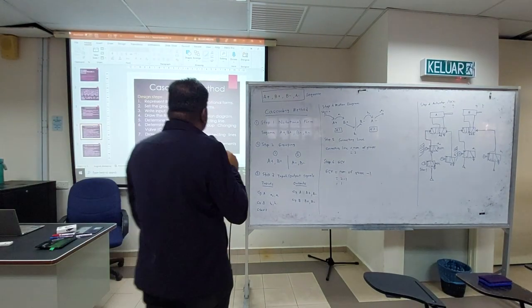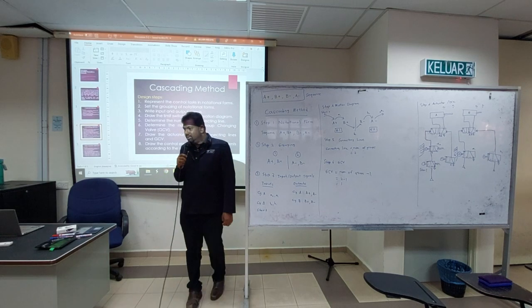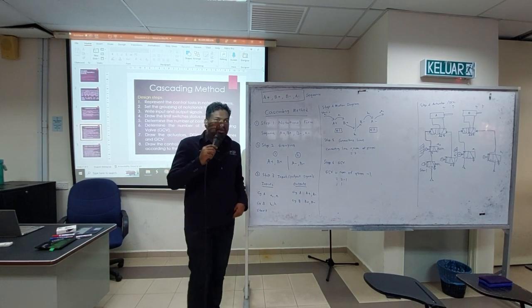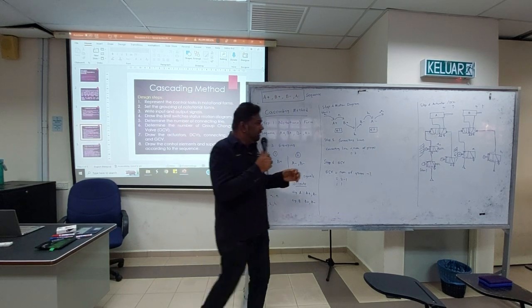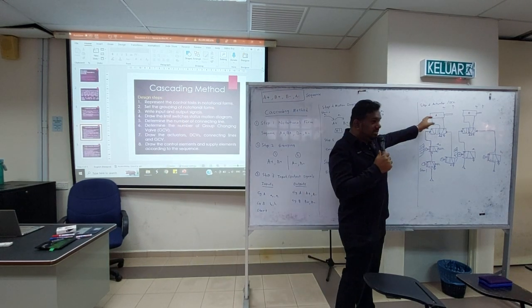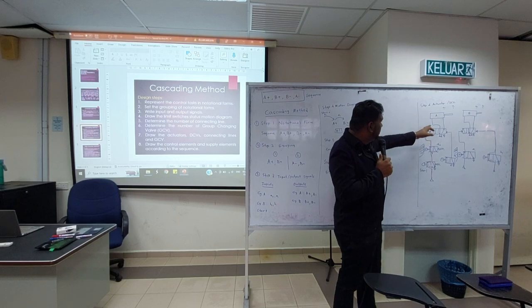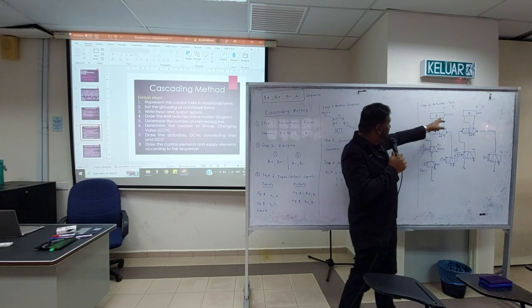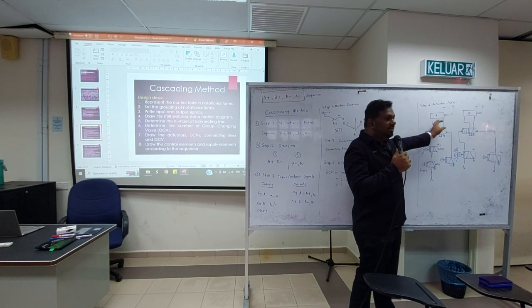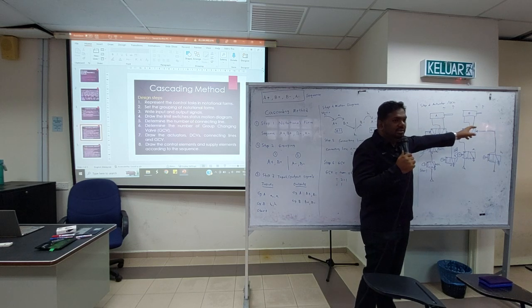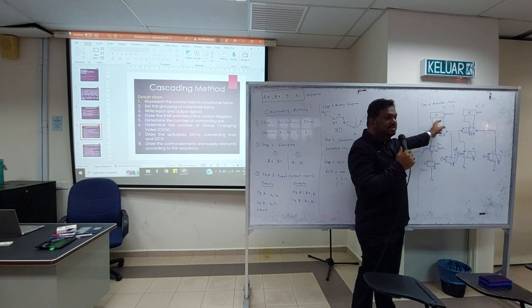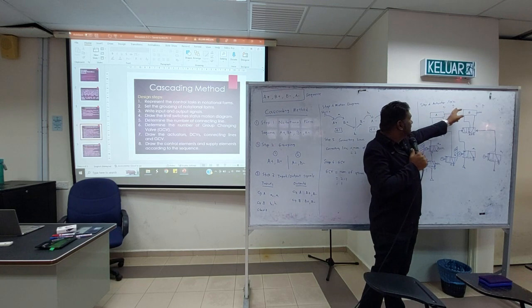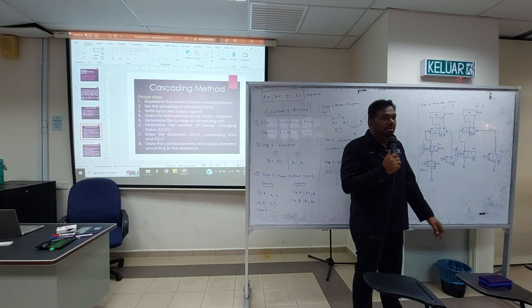So okay, we will continue with the cascading method. The cascading method is also quite important. Before that, the earlier circuit that we drew: if you see, the cylinder will be either extended or retracted. So for each sensor, each cylinder, either A0 or A1 will always be on.